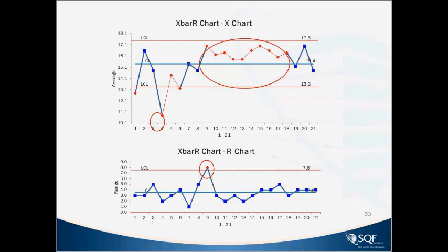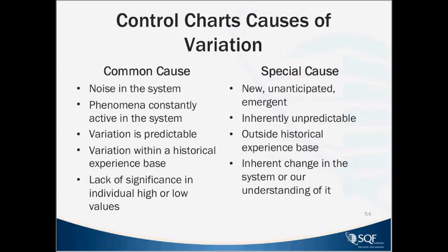And I think sometimes when we put specification limits on control charts, along with control limits, they can confuse the operator in terms of, when should I react and when shouldn't I. But if the control limits are there and those control limits come from their data, they should trust that. It becomes a very valuable tool to use.